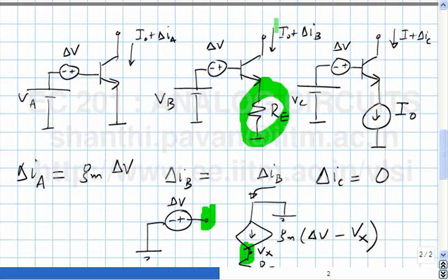So one sure shot way of looking at the circuit and figuring out if it is robust against transistor variations, which is equivalent to saying is the negative feedback loop strong enough, is to simply compare the drop across the emitter resistor with the thermal voltage VT. Does that make sense? So if the drop across the emitter resistor was 1 volt and obviously the thermal voltage is about 25 millivolts, the ratio is about 40.